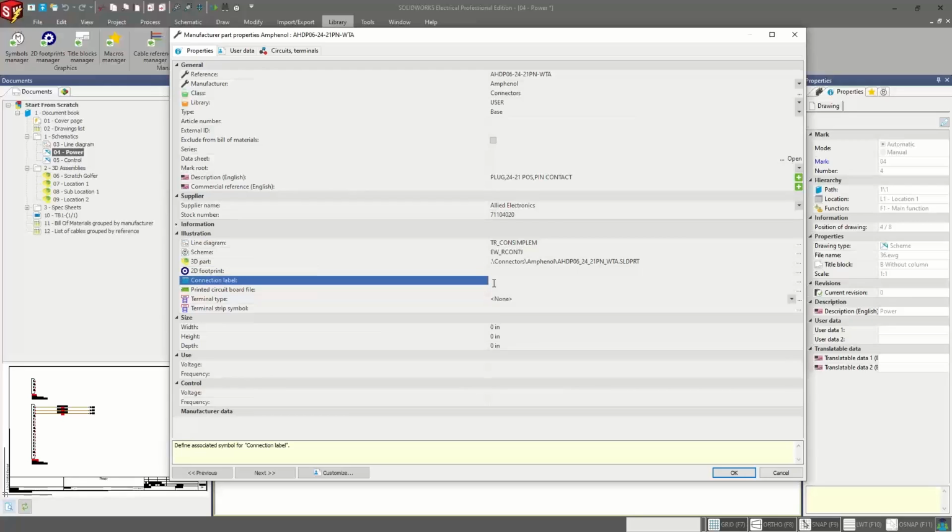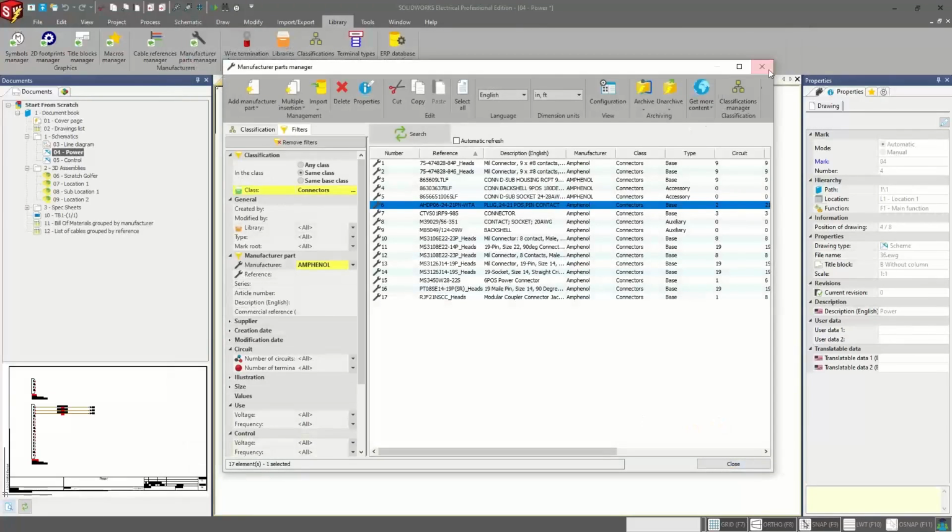So maybe I want to get a small table that I can drop onto my schematic sheet that includes all the pinouts and just give me a table. The nice thing about connection labels is that if I change the wires in my schematic at all, that will also reflect in that connection table that is associated to this particular connector. So those are the few different options you can have to associate these to it. Now, that's one way to add to this. I know I'm getting off a little tangent here. I'll go ahead and save that.